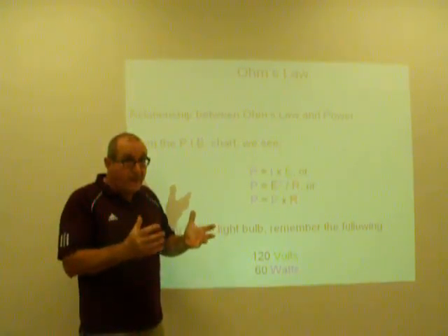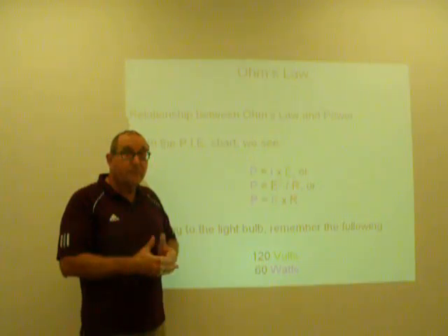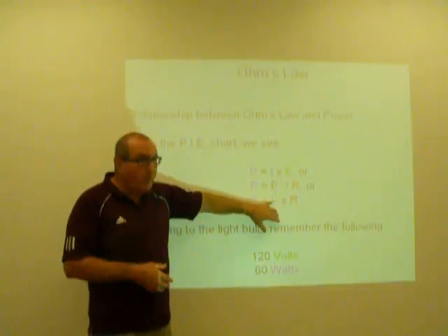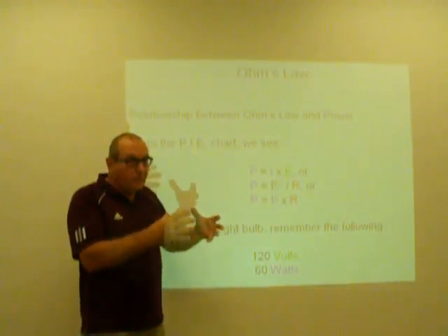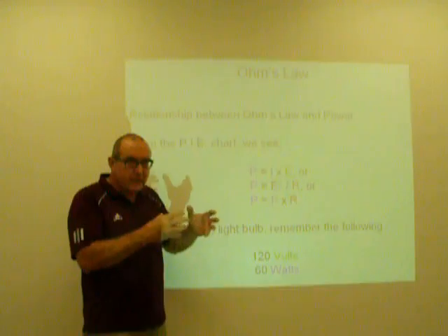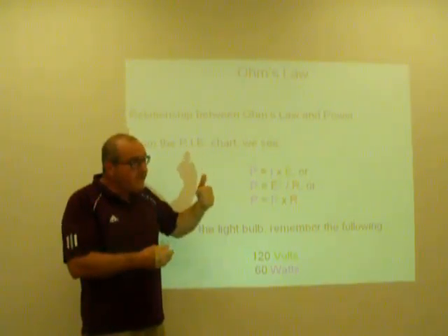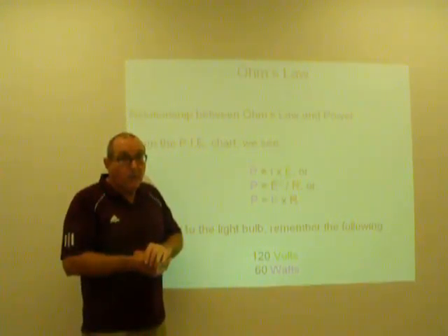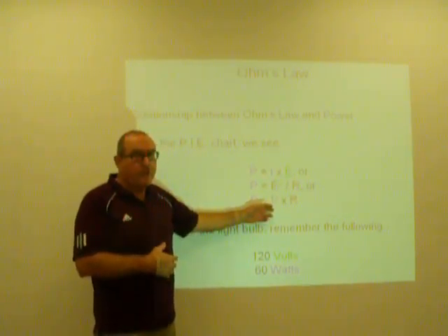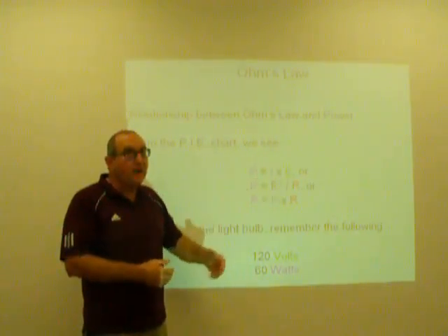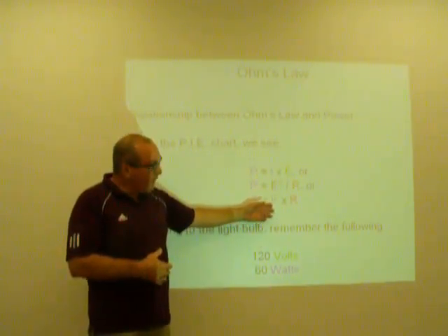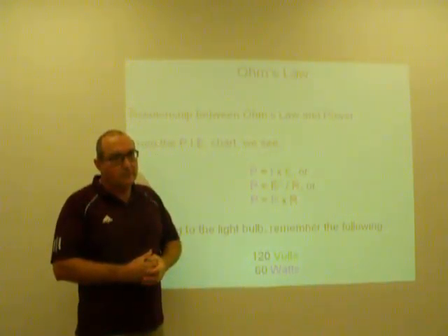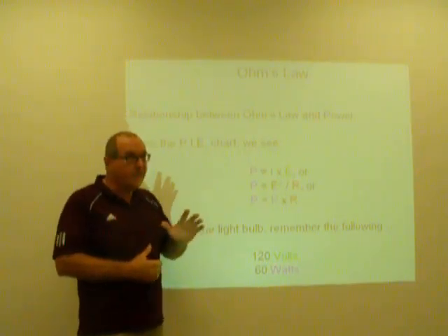because it turns out that the resistance of the wire causes a tremendous amount of what's called voltage drop, and the voltage drop is a function of the square of the current. Well, if watts is the amount of power being generated, it actually becomes a constant. So if we can raise the voltage really, really high, then we can drop the current really, really low. And as a result, you have a very low amount of current being carried over this wire at a very, very high voltage. And the square of a very small number is still a pretty small number. So your losses in transmission are incredibly low. So the power company loves that.